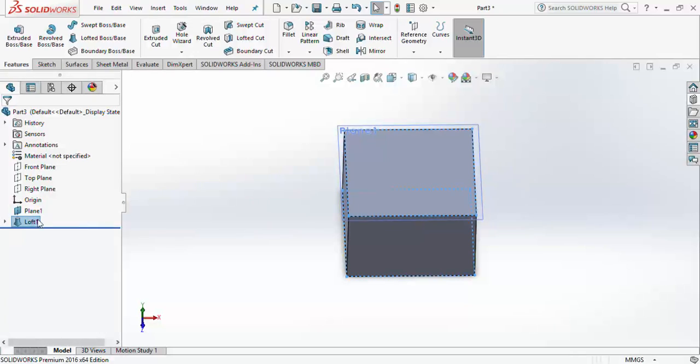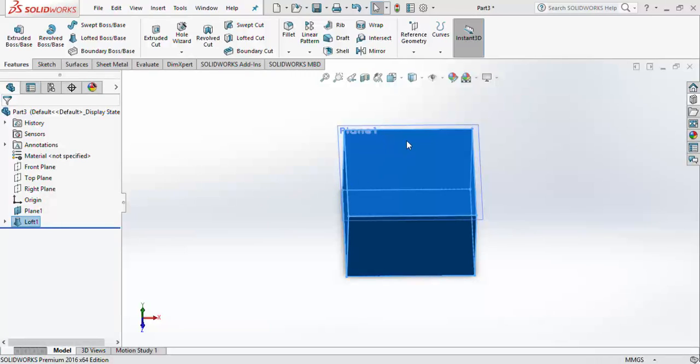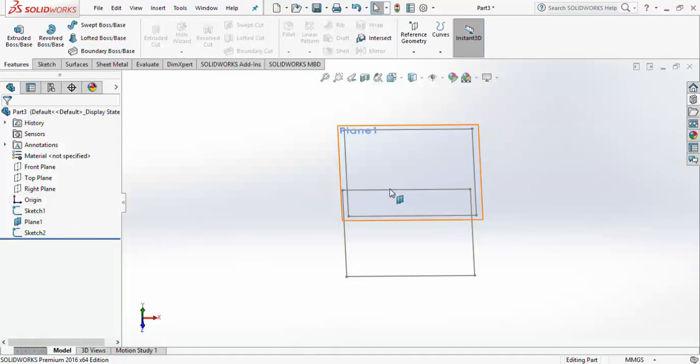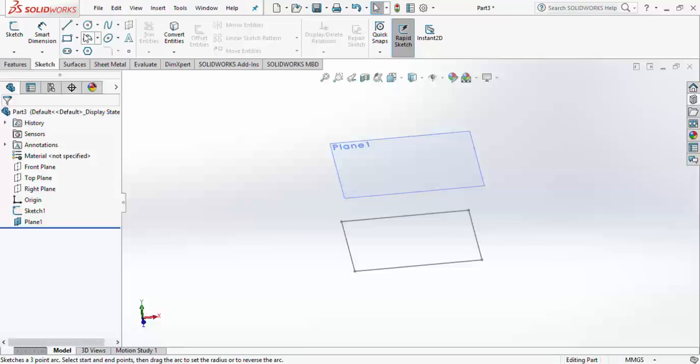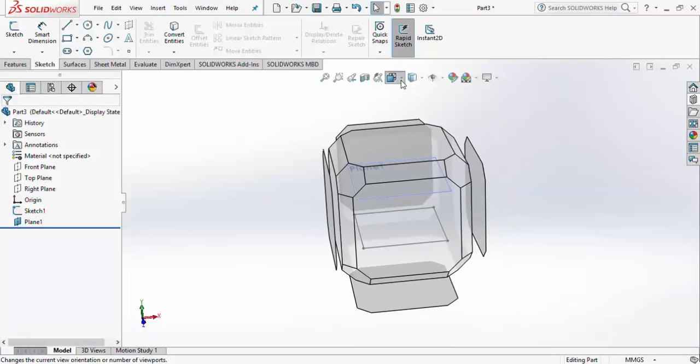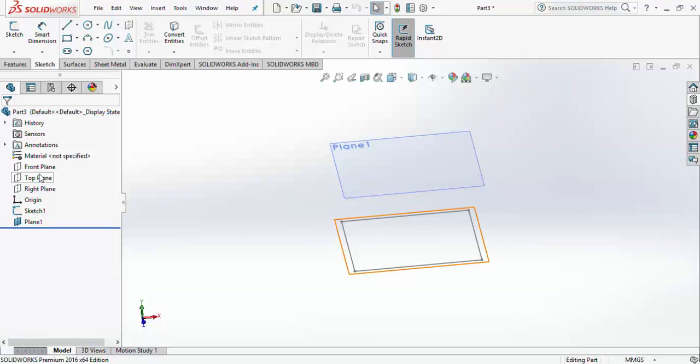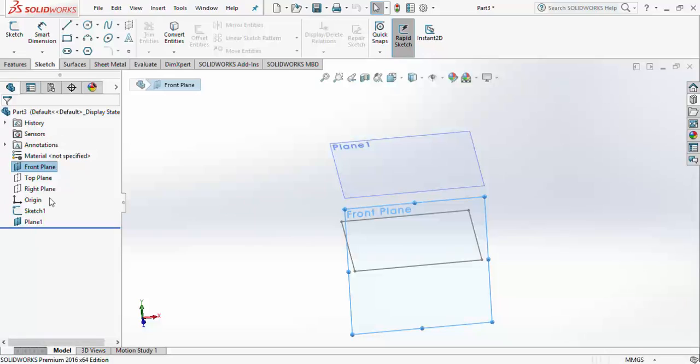The other way we are going to do it is, let's say, delete this one, and we've now got these two sketches, but this time we're not going to use the second sketch. We're going to use a sweep. Sweeping is going to be a tricky, different way of using this feature. Rather than drawing on some parallel plane, it will now be drawing on a perpendicular plane.